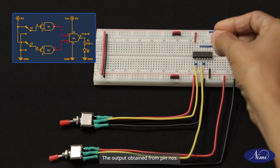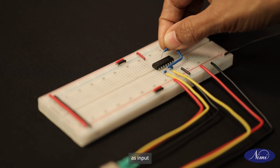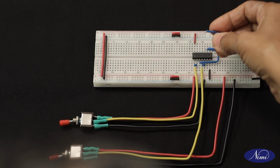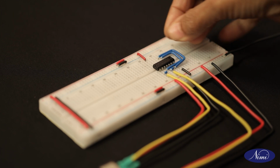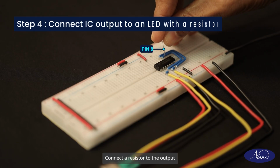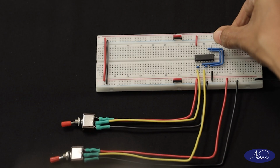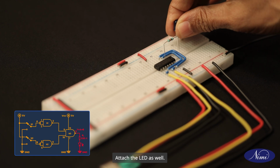The output obtained from pin numbers 3 and 6 are fed to the 9th and 10th pin of the IC as input, and output is obtained from pin number 8. Connect a resistor to the output pin number 8 of the IC. Attach the LED as well.